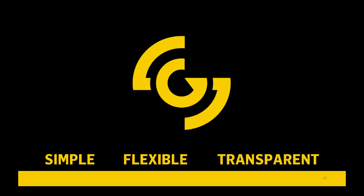So you want to check all of those parameters in the intersection, in the setup, and make sure that those are correct. And then if that doesn't solve your problems, one of the things that GRIDSMART has always enabled users to do is plug in a USB hard drive and record data. And we use that data to continuously improve our algorithms. This would be a great thing to use for, if in fact it's not a configuration issue. But my first thing to look at would be the north heading and all of the camera settings, and make sure that all of that is configured correctly.